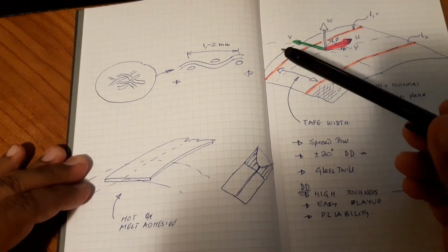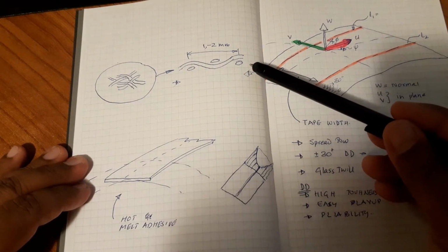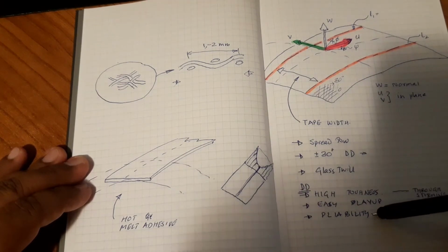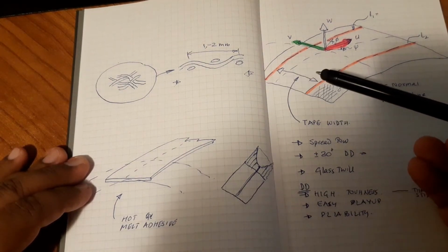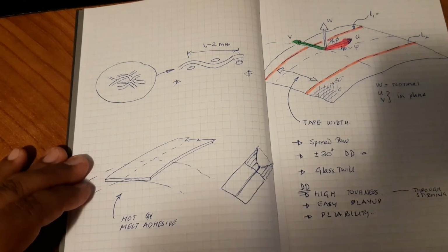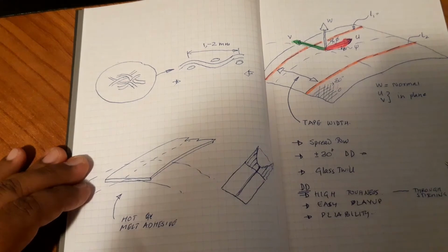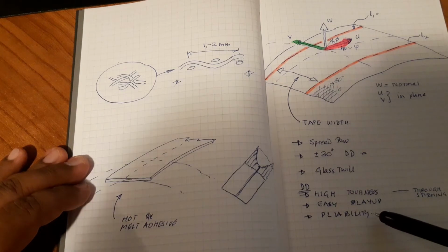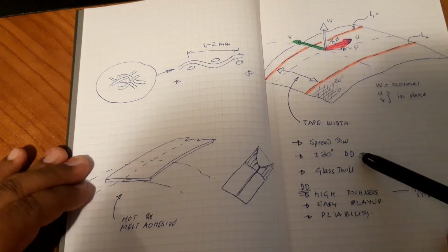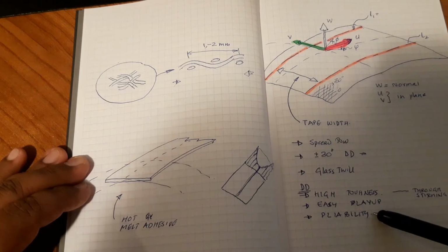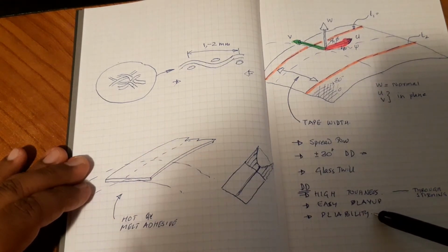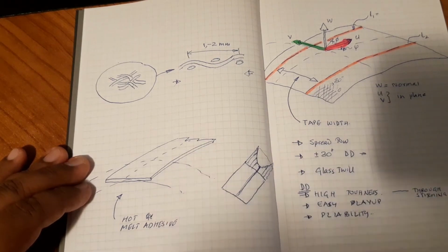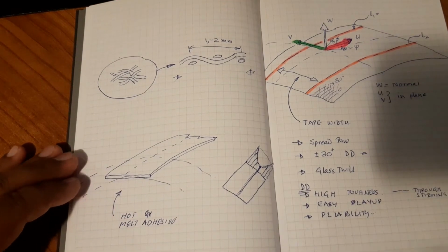Of course, the satin weave and the double twill weave of regular cloth will give you very high pliability, but they are not structural. And that is where DD or any other NCF, that is non-crimp fabric, will give you very easy pliability. It's not just DD. Any non-crimp fabric will give you very easy pliability, and it'll give you a very strong surface which has extremely high compressive strength. So now we'll go outside and I'll show you what I mean.